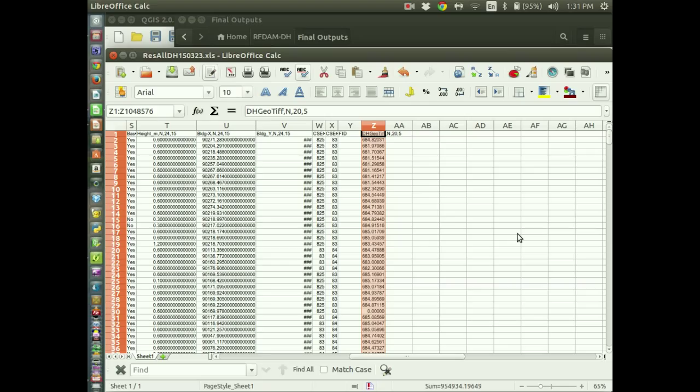Well, there is, but then obviously you would degrade the DEM, because the raw data is in UTM. So it's easier to move the points, drape it, and then move it back, because all you're doing is sampling the elevation of the location.